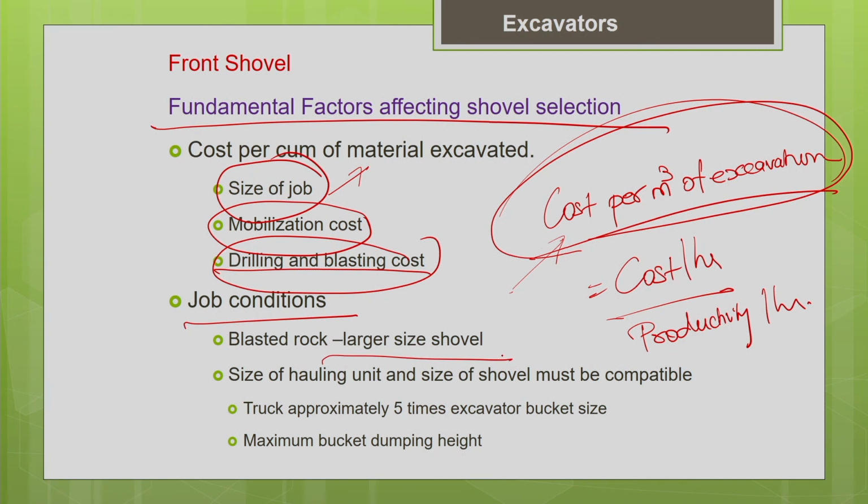I told you earlier, when you are going to handle the blasted rock, you need more effort, you need more breakout force, to loosen the material and dig it and load it into the bucket. So for that it is preferable to go for larger size shovel which can deliver more breakout force so that you can easily do the digging operation. So for blasted rock, preferable to go for larger size shovel.